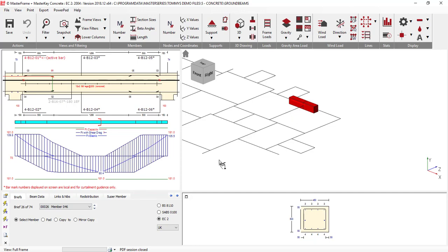Now clearly the designing with the torsion included is going to prevent any cracking that could occur. It's going to mean more steel, and it's also going to mean more complicated links, because the links must be what I would call a five-sided link, where you don't just join at the corner, you have to actually go round two faces to get your torsional links, and it makes that note here for them. And that's fine.